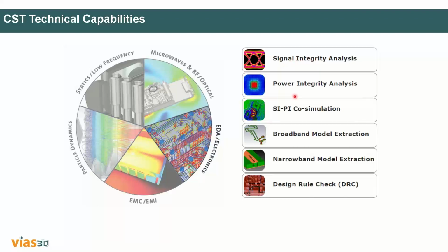You apply some power. Obviously, the maximum power transfer theorem will tell you that you are not going to get the complete power output, right? You can expect a maximum of 50% of the power output if you have impedance matching. But however, that is also not possible because of a lot of power drop. And where is the power drop happening? So we have to study that. That kind of thing is there in the power integrity analysis.